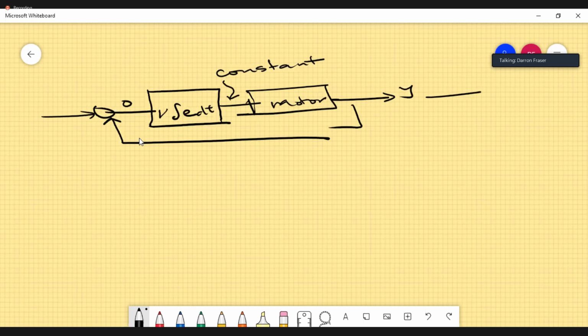The Ki is how much you multiply that constant by. The tuning for the controller is that you take the error and multiply it by a constant. The constant value you get is going to be of the order of milliamps or millivolts, still small and non-zero. So you still have to multiply it by a gain to control whatever it is that you want to control.